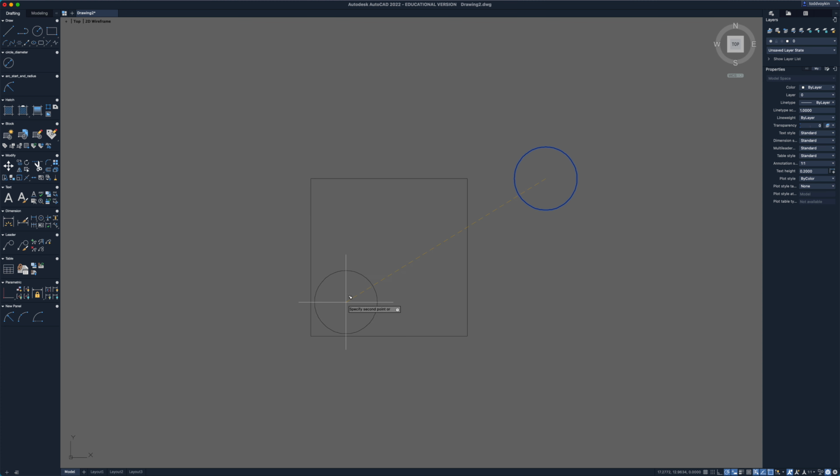I'm going to come down here and touch this point right here and slide over. Okay, and now I can type in 5, enter, and it's 5 to the left of that and perfectly in line with the bottom corner. Okay, I can do the same thing with a rectangle. If I make a rectangle, I can line it up with this bottom corner and start right here like that, and those are perfectly in line.